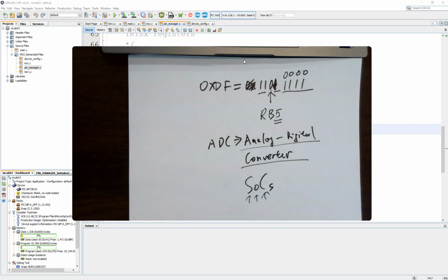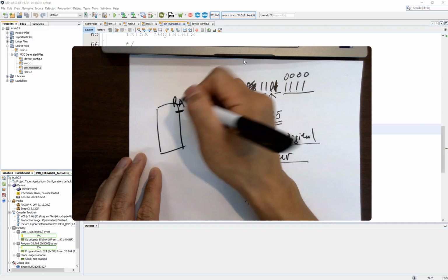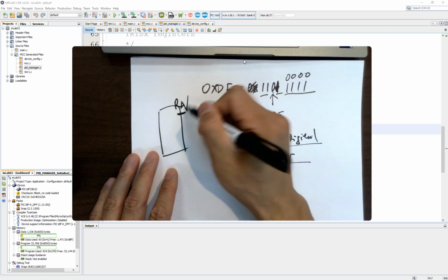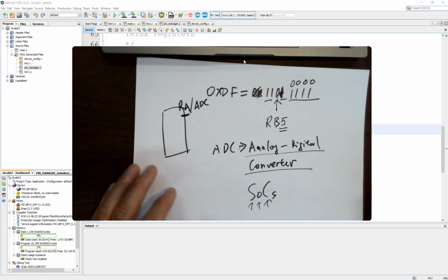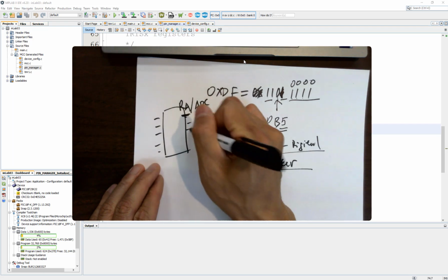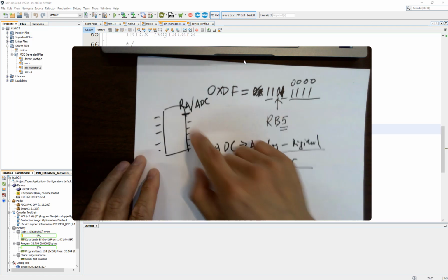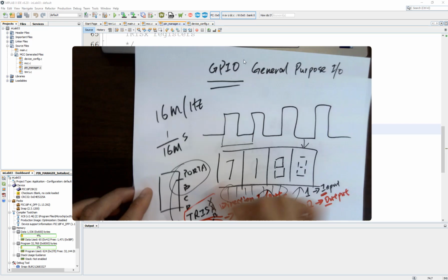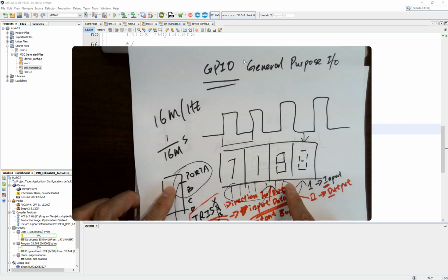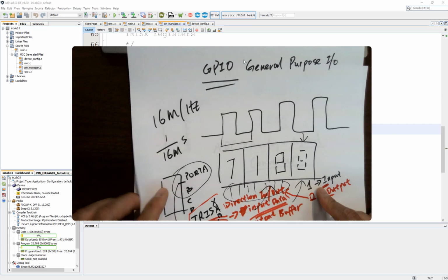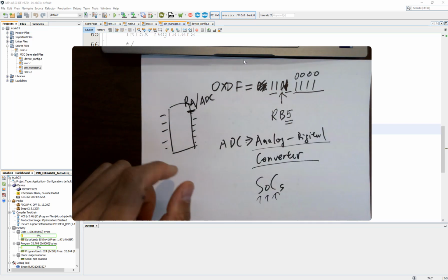Okay, we're not using it, but some of the pins, for example, the A ports, I'm not quite sure, but just to give you an example, the A ports could be multiplexed. Why do you want to multiplex it? If you just look at the chip, it doesn't have many pins. You've got power, ground, and other things, but if you connect one 7-segment display, and 4 pins for the switch, and 7 pins for the data, plus power and ground, it takes up all the pins. You couldn't do anything else.